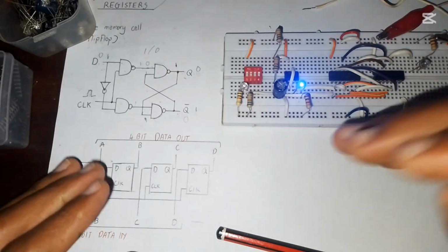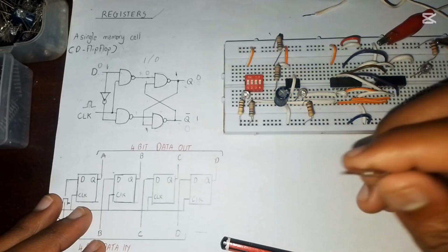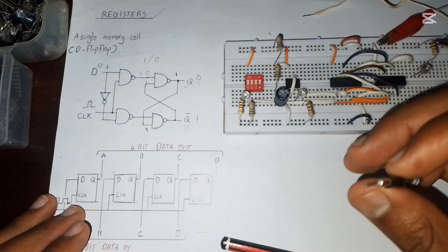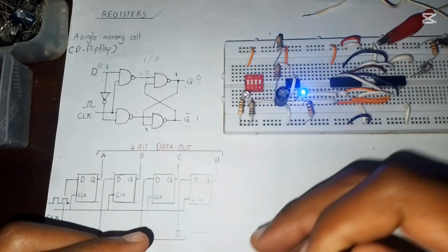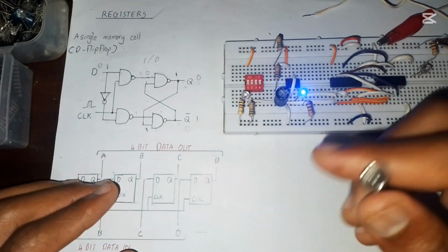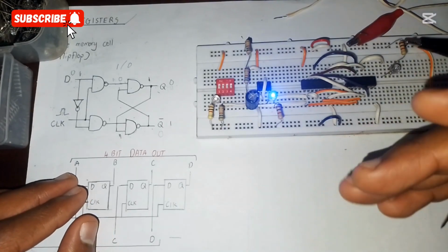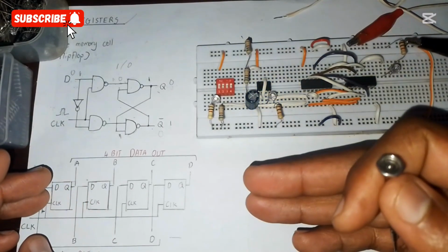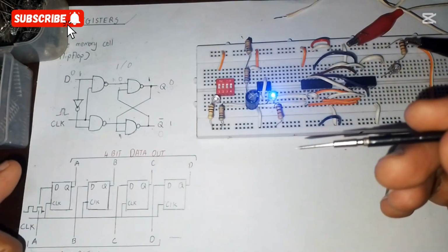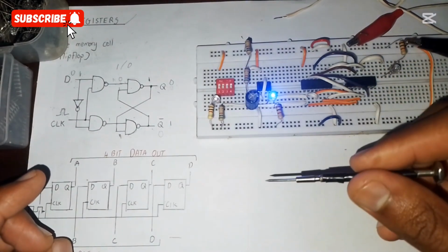So this is a very good introduction on how we are going to learn about registers. Next time we are going to check on different types of registers. We have serial input, serial output, serial input, parallel output, parallel input, serial output, and so on. And we are going to demonstrate them. We are going to even connect them. Then finally we can even connect an ALU to a register when we want to store that data. If we do an arithmetic operation and we want to store that data into a register, then we are going to make such kinds of connections.